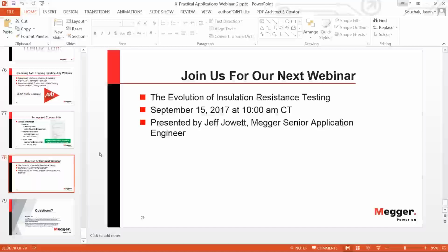Okay, you can also look at leakage current. If you use the cosine rectangular VLF unit, you do a withstand test with leakage current, or you can do a monitor withstand test. The monitor withstand test on the other side is really a great tool, in my opinion, to do a commissioning test, because you do a withstand test at a fairly high voltage, 3 per unit, the highest test voltage that we use. You look at PD level at that voltage level, and you can also see whether you have any leakage.